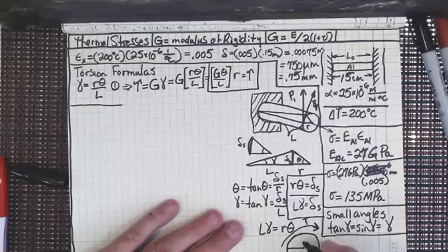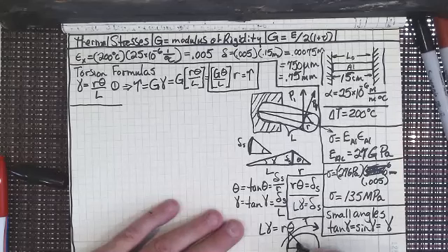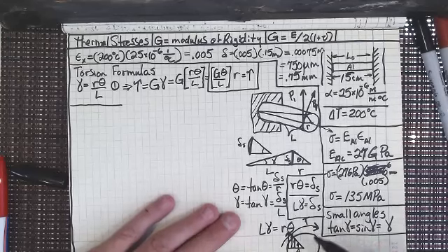Well, the force is being resisted from the center in. So really I have P distributed from the center out, because it's dependent upon rho, the distance out, and each one of those small resistive forces is along that line, all resisting the applied force P.